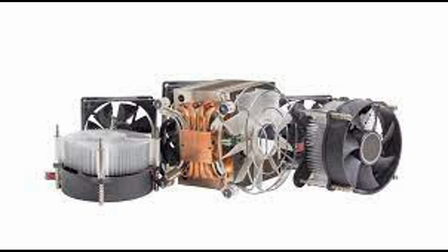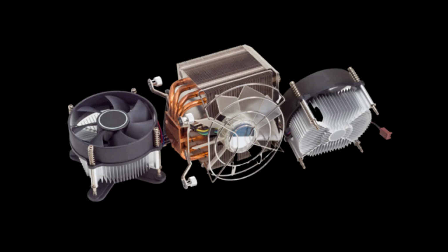Pin-fin heatsinks can achieve high heat dissipation capabilities while occupying minimal space, making them suitable for compact electronic devices where space is limited. Versatility. Pin-fin heatsinks can be configured in various shapes and sizes to accommodate different cooling requirements and fit specific application needs. Uniform airflow. The cylindrical pins create channels that help guide airflow, promoting uniform distribution and efficient heat dissipation across the heatsink surface. Lightweight construction. Pin-fin heatsinks are typically made from lightweight materials such as aluminum, making them easy to handle and install.